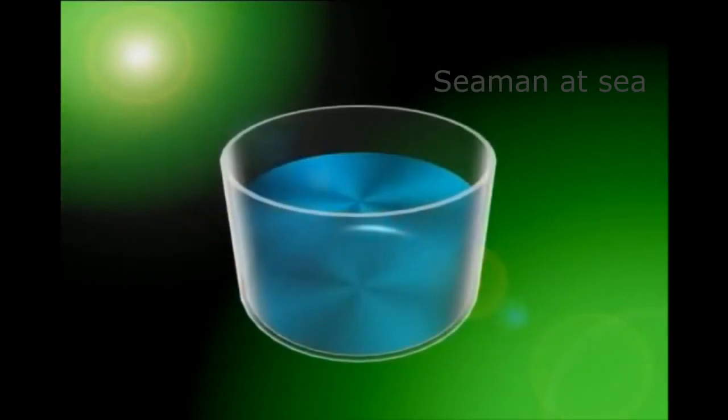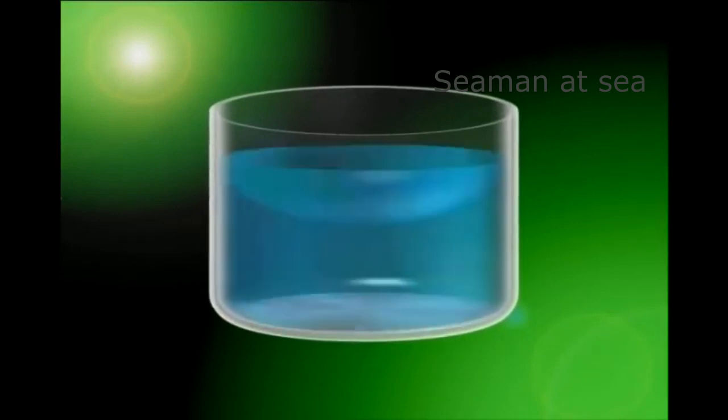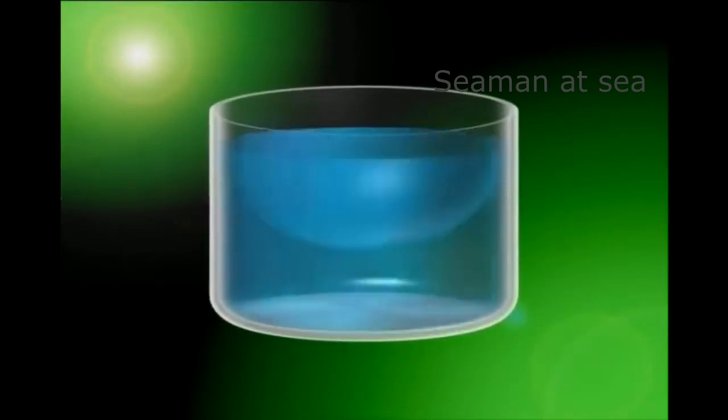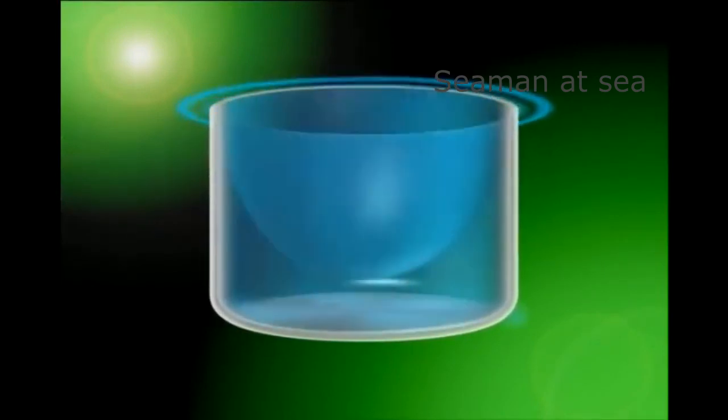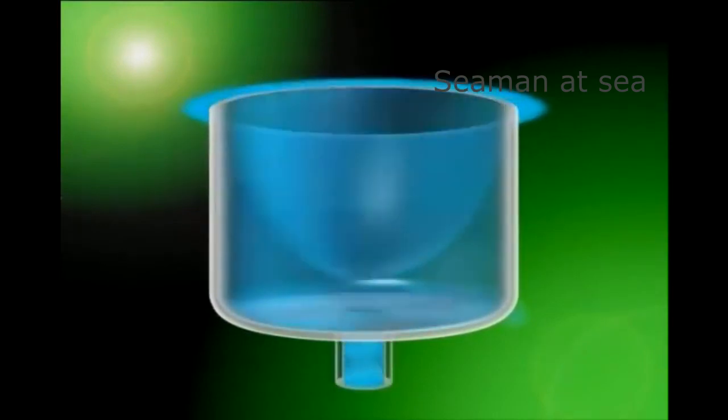Put some water in a cylindrical container and turn it around the container's axis as the center of rotation. A centrifugal force works on the water and pushes it toward the container wall, making the water surface form a parabolic arch. As the rotation speed is increased, the centrifugal force becomes stronger to such an extent that the water goes over the container's brim and spills out.